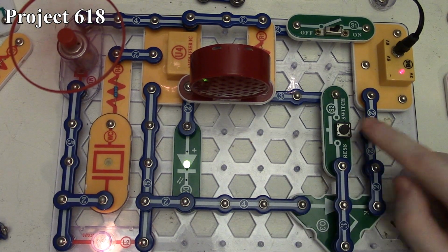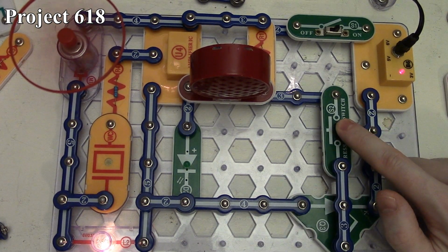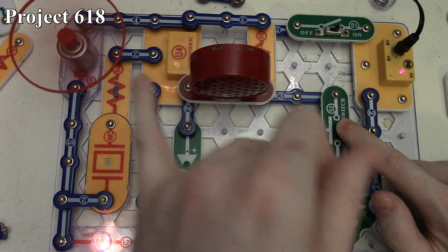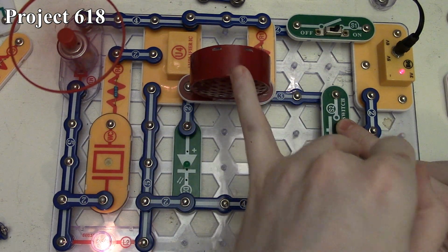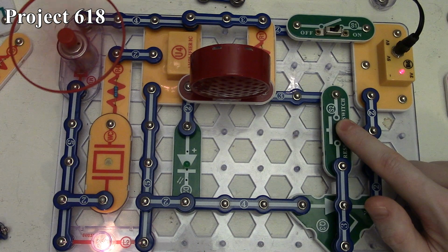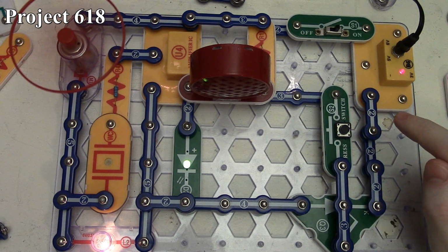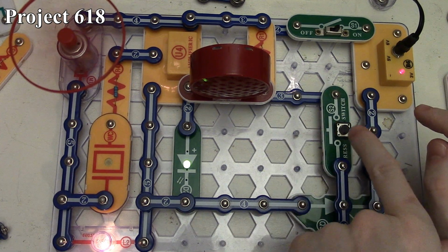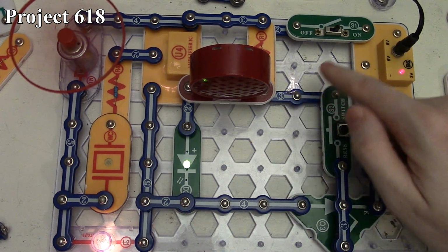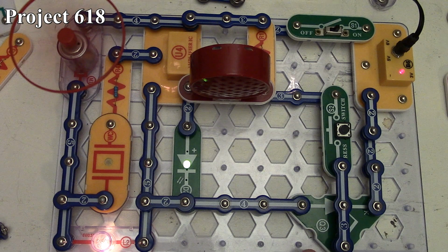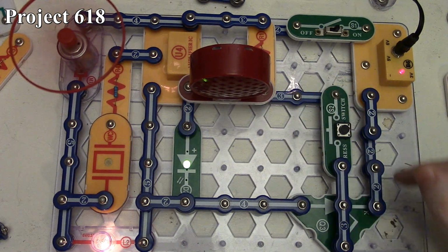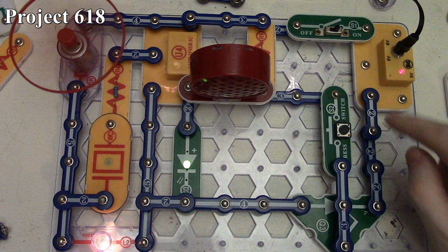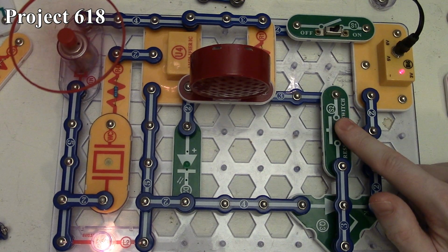Now if we press and hold down the press switch, the noise from the motor gets louder from the speaker, and our green LED goes off. And the reason for that is because when we hold down the press switch, we're actually using the gate of the SCR here to provide some more current passage through our amplifier here back to ground.